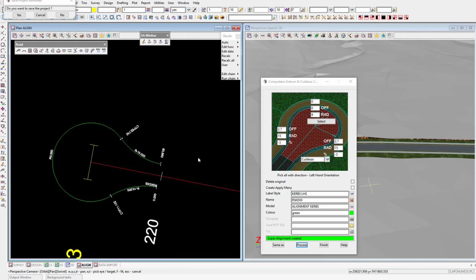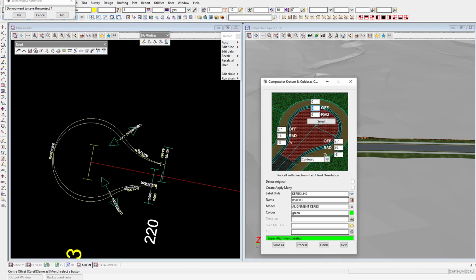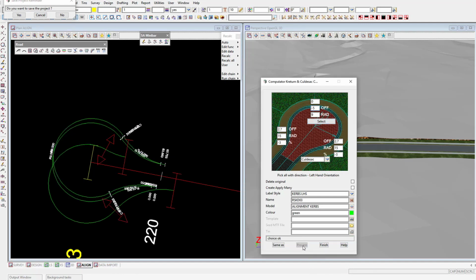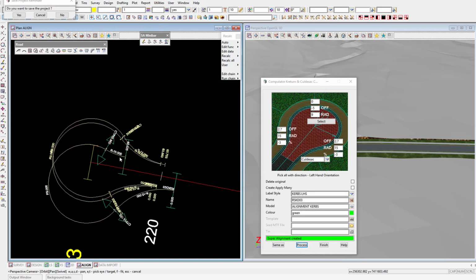Okay, and I can fool around with the dimensions of that cul-de-sac, or the parameters that you type in here. If I wanted an offset of 1, I'll just do that, offset of 1. It'll draw it and offset it 1 meter to that way, to the positive offset. If I wanted an offset of, say, -5. So it's doing the complicated geometry for you. It's now produced this one in here, okay, with an offset of 5.